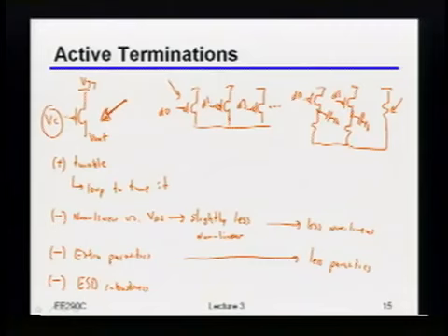Yeah, so there is certainly a trade-off here in terms of how you size these resistors, in terms of the maximum step size you get versus the number of unit elements you really need to deal with. The good news is that, remember, we're only dealing with plus minus 20%, and I probably only need to knock that down to like plus minus 5% or so. So I'm not trying to build a 0.1% precision resistor here. I'm just trying to get this to within the range where it basically doesn't have an effect on my overall signal integrity anymore. But you're absolutely right. It's not that this is a slam dunk. It's got its own design issues.